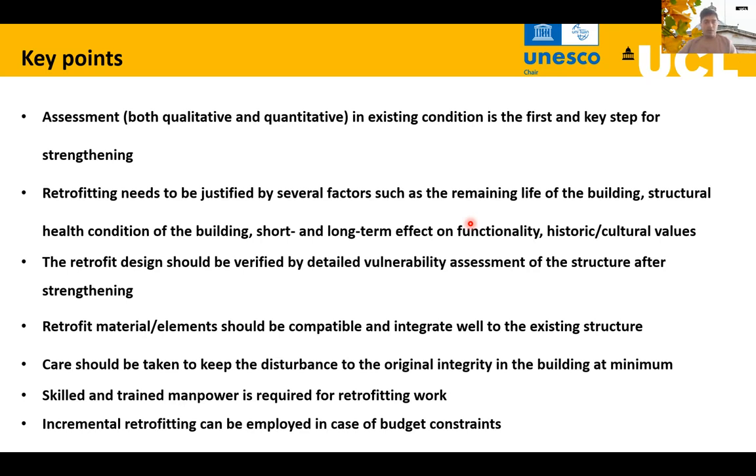We also need to identify how much cost the retrofitting incurs, how much historical or cultural value the building has, and how much disturbance to our functionality is caused by the retrofit work. The retrofit design should be verified by detailed vulnerability assessment, as I showed you in the previous slides. The retrofit material and elements should be compatible and integrate well with the existing structure, as you also saw in Juan Carlos' presentations. Care should be taken to keep the disturbance to the original integrity of the building to a minimal level.